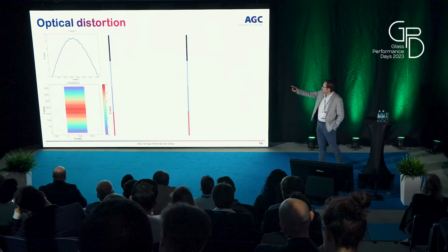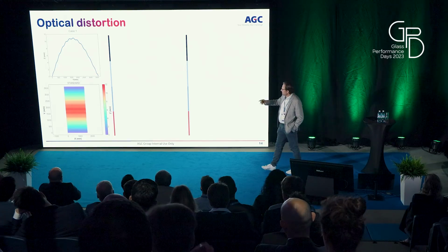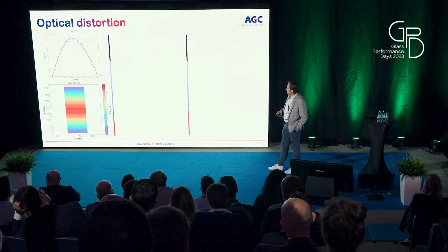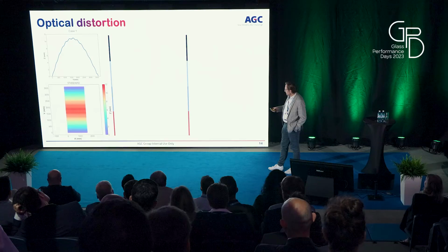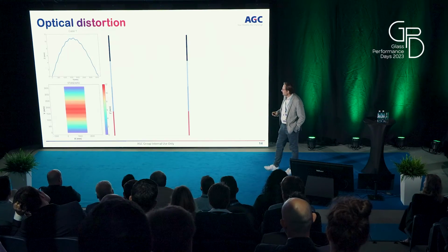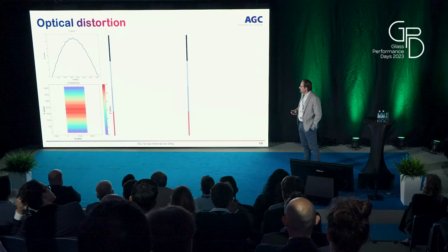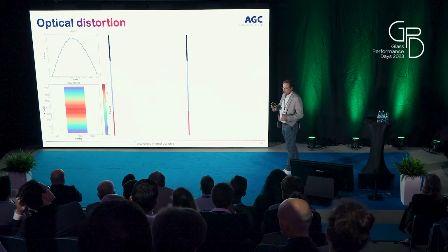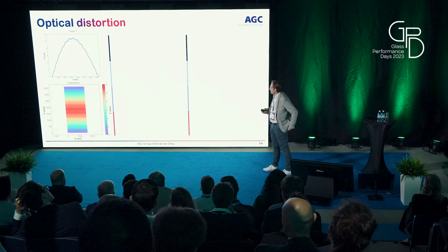You see here the extent on the top for each case, and on the bottom you see already the pane, 1.6 by 3.6 meters, and how the extension is of the overall bow together with the roller waves and the edge dip. The edge dip and edge lift is mainly on the leading and trailing edge, and the roller waves are all over the height, and the overall bow, it's clear, as a matter of fact, is like a bowl.